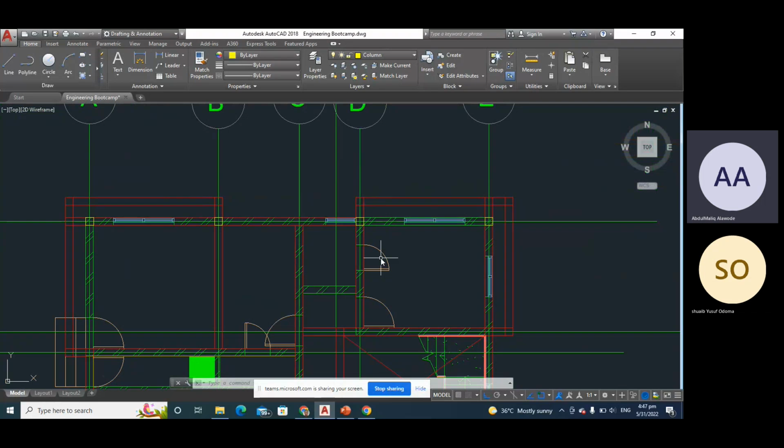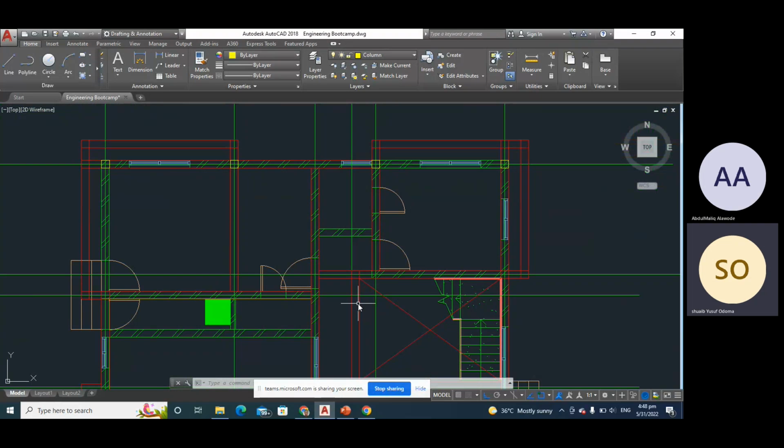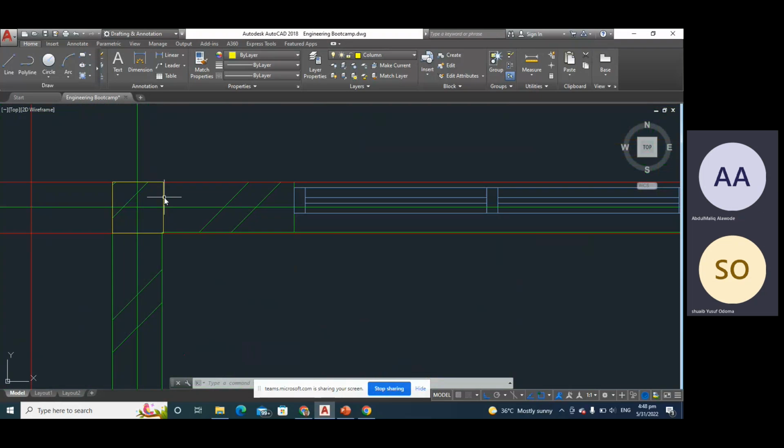So that was why I told you that if you have a 230 by 450 beam, you should make sure the effective length of the beam is not greater than 6 meters. Because once it's greater than 6 meters, there is a high possibility of failure, even without doing any analysis or design yet. Do you understand my point? Yeah. Good. So now let's move on.